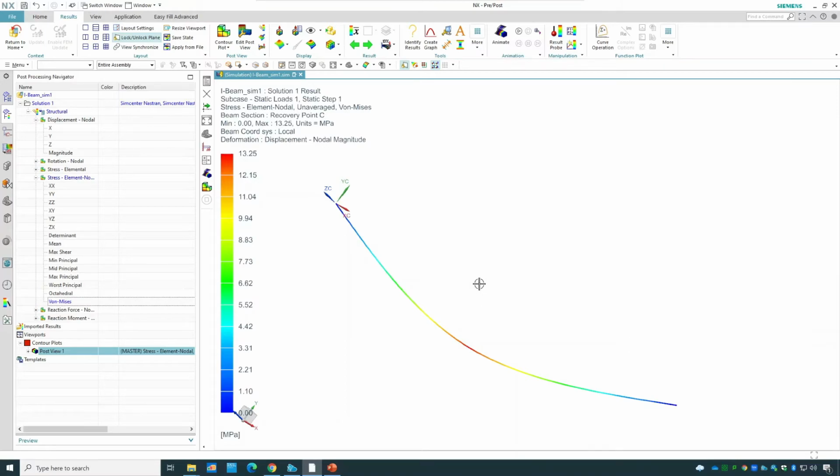So what we've done is try to simplify the I-beam to study it as a line. In order to let the software treat it as an I-beam, we applied the 1D mesh, because 1D is a line, and basically applied the beam section and studied it like that. This is one way of studying bars, for instance. What we're going to do is continue with one more tutorial.